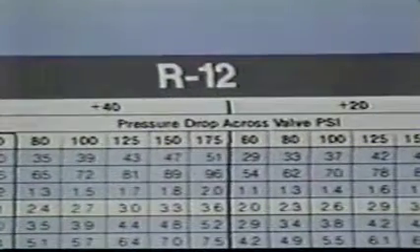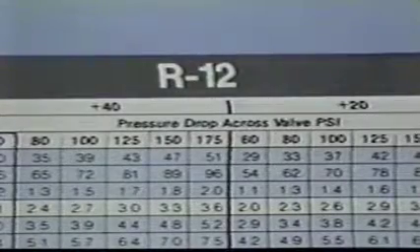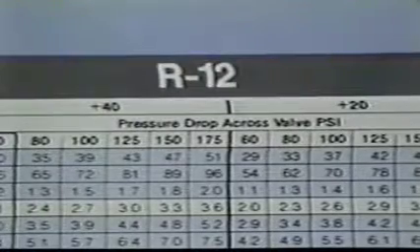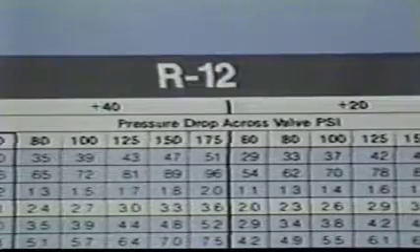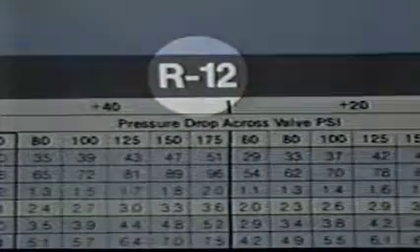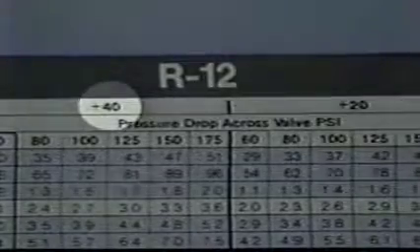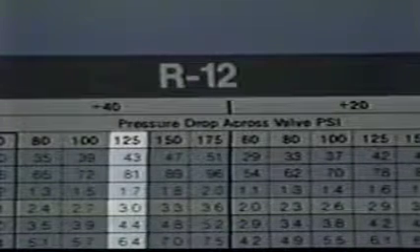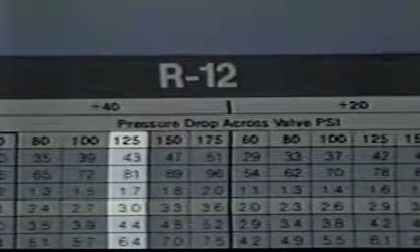To select a valve that will properly match system load, the user must choose from the full extended capacity chart. The extended chart will give the precise capacity for any valve under all possible operating conditions. By first selecting based on refrigerant, then evaporator saturation temperature, then pressure drop, the user can quickly find the valve that will most closely match his particular system.